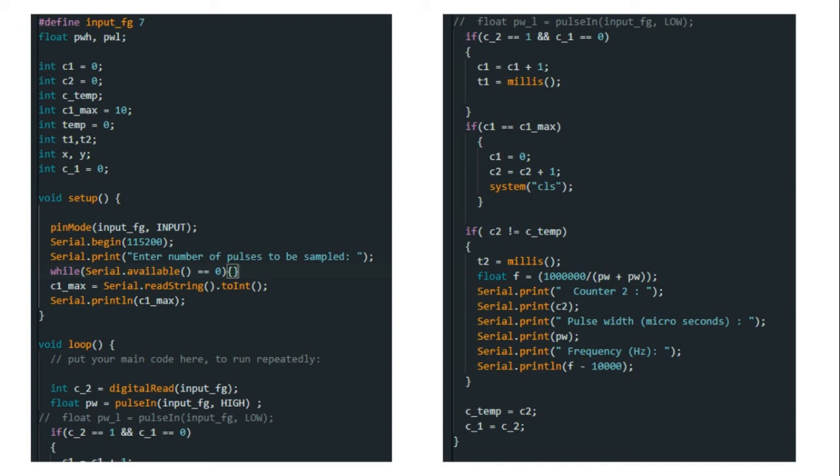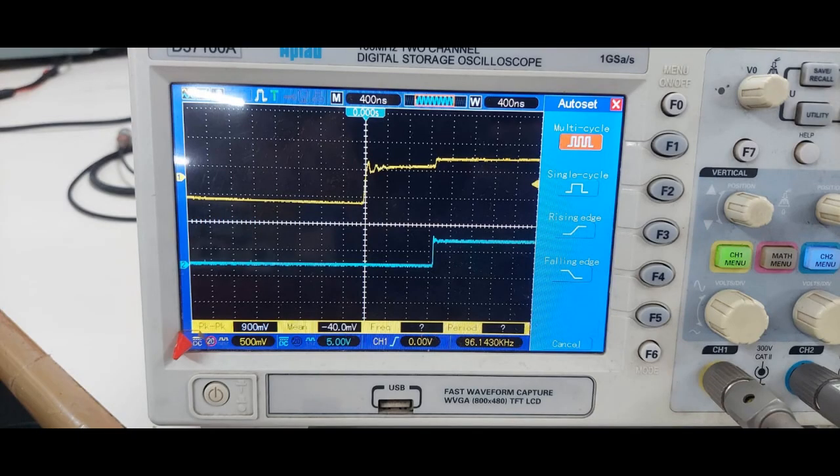In the program tried and tested here, we have counted the number of times when state changes from 0 to 1 to count the number of pulses. And for the second counter, we have grouped the pulses in a specific user defined set. Thus, the higher the clock frequency of the CPU, the lesser the time period it can read, which is very favorable for us if we want to work at higher frequencies.